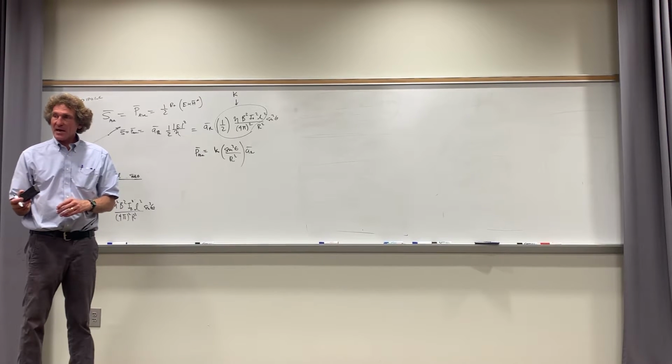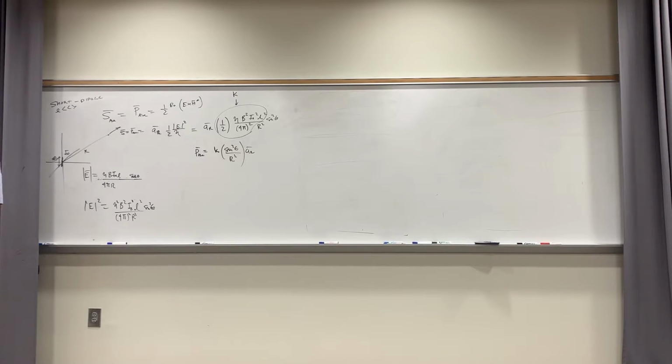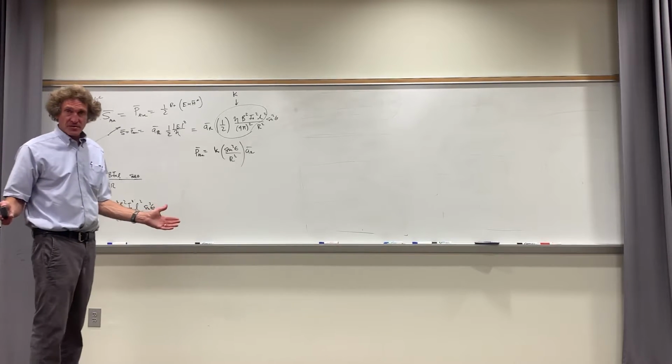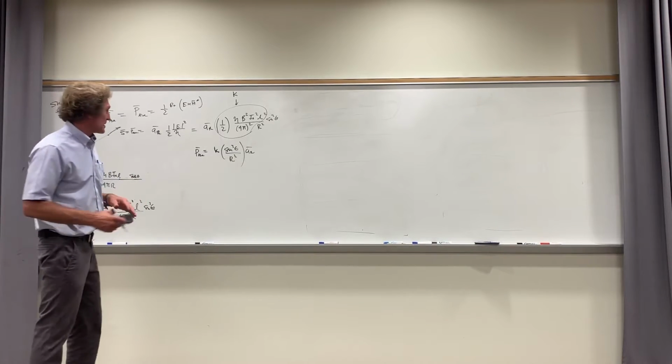Now what we're going to do is calculate the total power radiated. The way you do an electrical engineering problem or an antenna problem, especially if you're writing code, first you have to find the electric field in the far field, or magnetic field. Then after that, you calculate the power density. And then you have to integrate the power density over a surface far enough away so that there's no near field energy involved. And then we can equate it to something that's important.